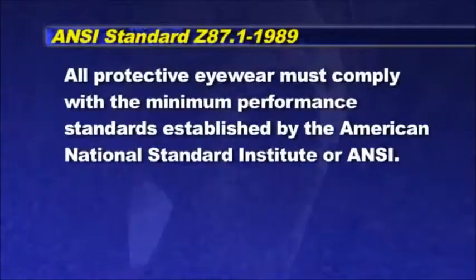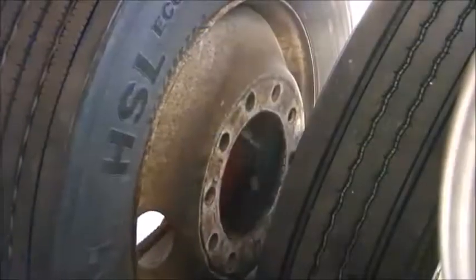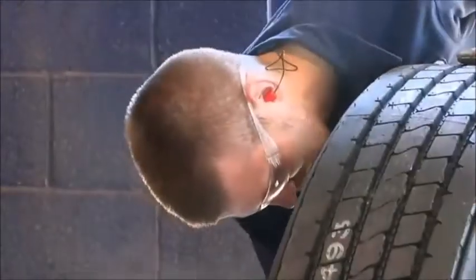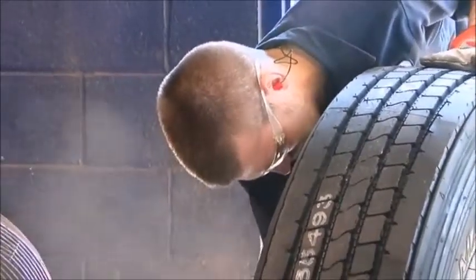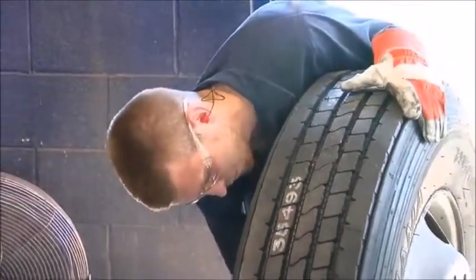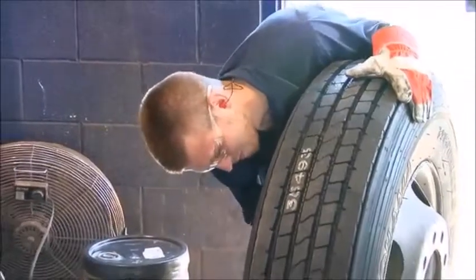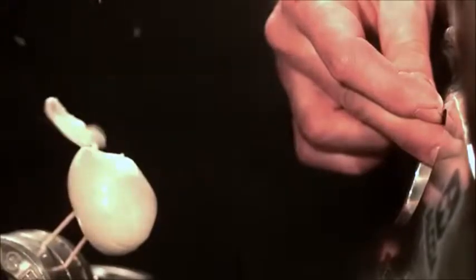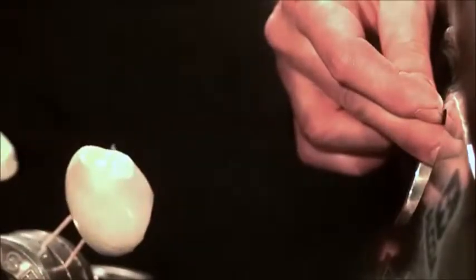All protective eyewear and face shields must meet the minimum performance standards established by the American National Standards Institute, or ANSI. The dangers associated with tire service are real and must not be ignored. Sunglasses will not protect your eyes in the event of an accident. In this test, a hard-boiled egg is used to simulate an eyeball and is placed in the trajectory of a valve stem. At 100 psi, the valve core can create a serious hazard for anyone without proper eye protection.